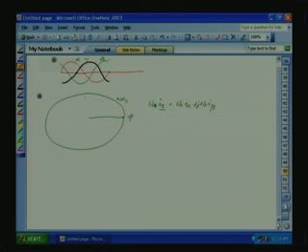So, even though this rotating flux is produced by three phase quantities, we can also have an equivalent two phase quantity, alpha beta. So, this is the flux which is already there in the air gap. Now, this flux is proportional to current. If you remove this Ns, which is a constant, then we can have a definition for the current space phasor. This is equal to I alpha plus j I beta. This is called the current space phasor. Space phasor or vector, anything is okay. Both are the same.